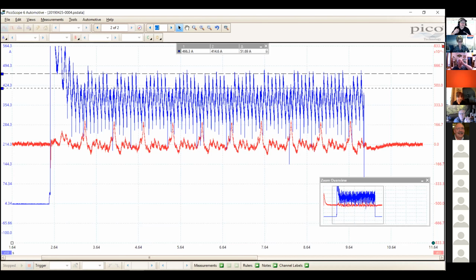Now, whether you're dealing with rings, whatever, I'm not going to get into that part of it, but I would never be able to expect the scan tool to run and complete the back pressure test if I have 2 cylinders that may not even be contributing. And I know the argument, I've been doing this a long time. Well, Adam, was it running rough? Yeah, it ran horrible when I got there. I just need a starting point, and that was a dang good one.